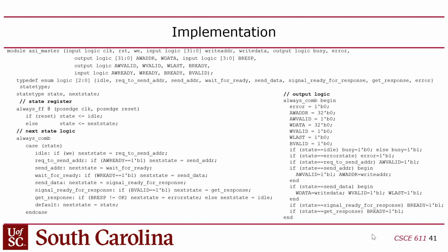And so that's an AXI interface for writing anyway. In reality, it would have to support reads too, so it would be bigger than that. Any questions? Of course, you'd have to design one of these for the other side too. This is for a master port. If you had a slave port, you'd have a similar arrangement where you have a state machine that interprets things from the bus and then puts the values out to the user logic.